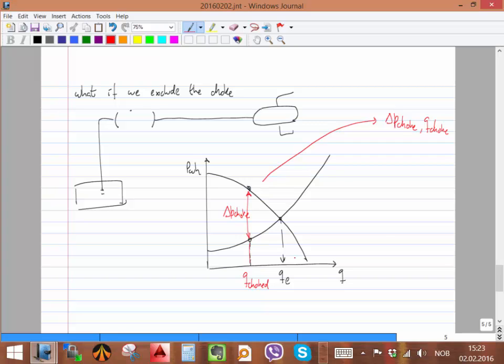Now what happens in the other case, where I want to produce a rate that is higher, that is at the right side of the equilibrium point? What's going to happen in that case? Can I do it? You need a pump or a compressor. I need to bridge this, I need to supply more than what I have available from the reservoir, I need to increase it so it will reach what I require from my system. So in this case, if I'm talking about gas, I can put a compressor at the wellhead.